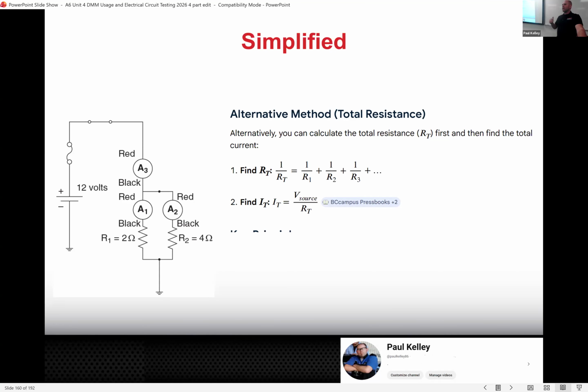But then it'd be like, well, hey, the book also says put a battery charger on it when you do the compression testing. You didn't do that, right? So I don't think this tech was trying to rip the customer off. The engine's not even really a good job to sell. It's not even a profitable job in a way, but it's a hard job.